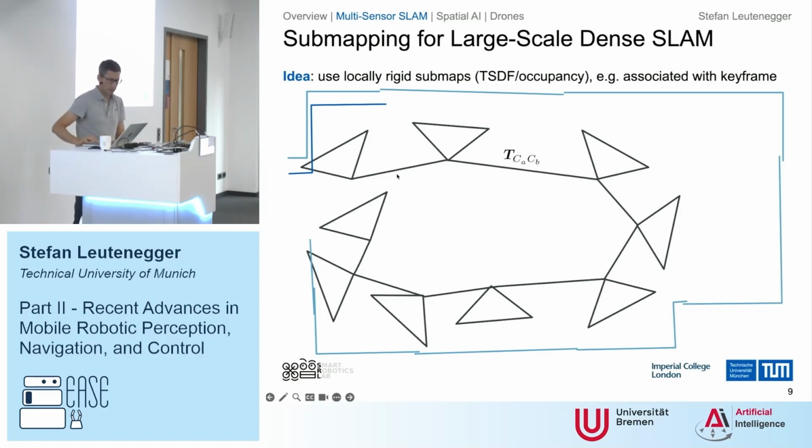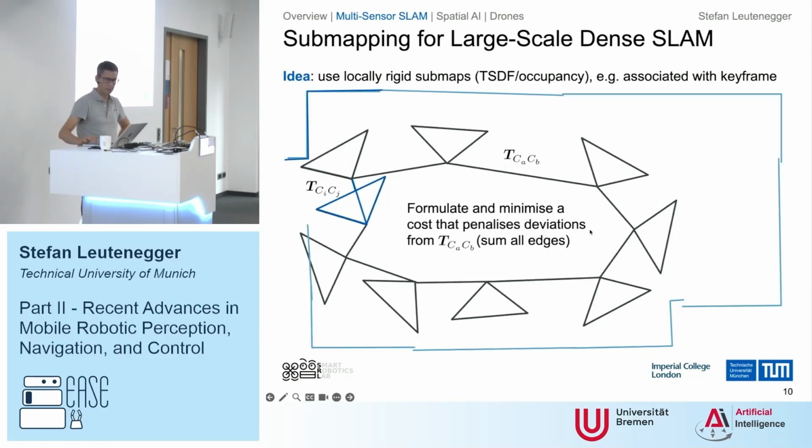It's a simple standard approach that instead of having just one global map, you will have submaps, and the submaps are anchored to the keyframes here. So you'll have one submap per keyframe, and now when you have a loop closure, you're trying to deform this pose graph, and the map is deforming with it, in the sense that the individual submaps are being aligned together with the keyframes that you have aligned, and you have mitigated this inconsistency.